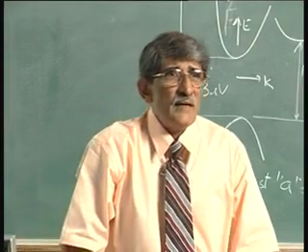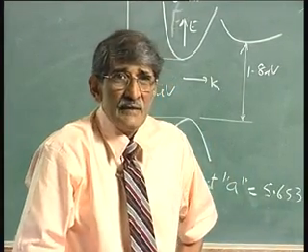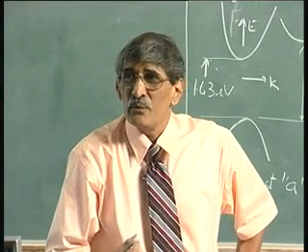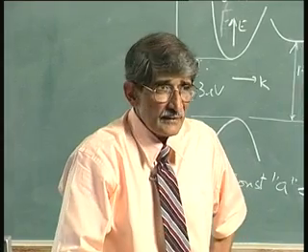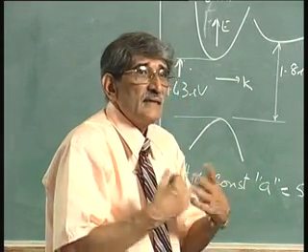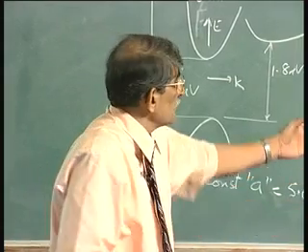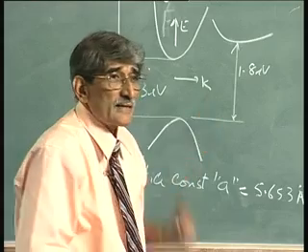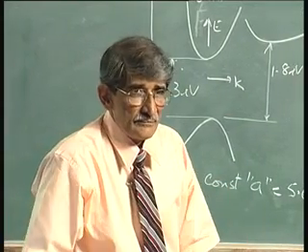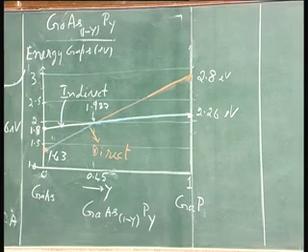So, the most interesting part of this diagram, or this exercise, is you can make use of ternary compound semiconductors by mixing binary ones. Whether it is direct or indirect depends upon the composition. Here Y, that is the phosphorus mole fraction, as it varies from 0 to 1, you will go from direct to indirect. What is the key thing here? Now, you can actually use